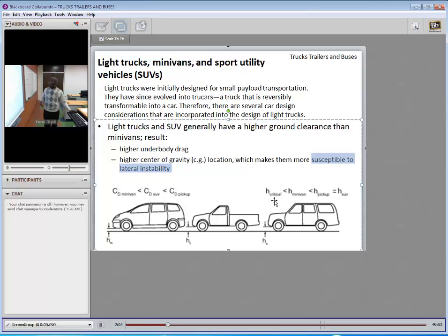We're looking at the critical height, the height up to which we can raise the underbody of the vehicle to avoid lift or lift tendency from the vehicle. Beyond that height, we're actually having separation of bodies, and we undo the benefit we get in the drag reduction and lift to the vehicle. So that critical height for the minivan is the lowest when you compare all three of them.